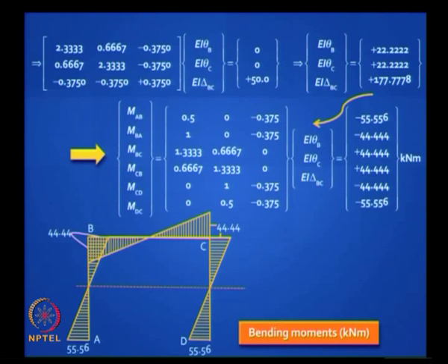Now look at this problem. I am going to raise a question and we will stop this class. There is something nice about this bending moment diagram. What do you call such a figure? It's not symmetric, it is anti-symmetric. So that gives you a clue. It's anti-symmetric and the moment at the middle of the beam is 0. So maybe we could have taken advantage of this anti-symmetry.